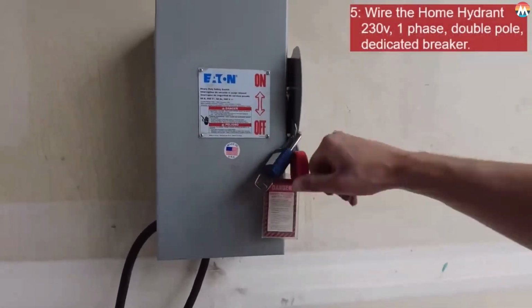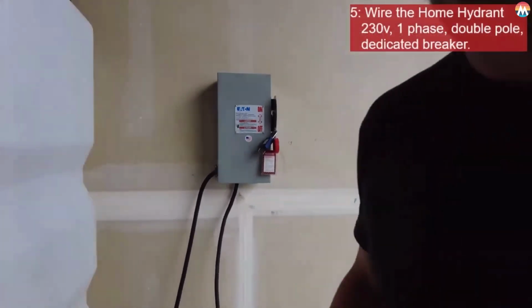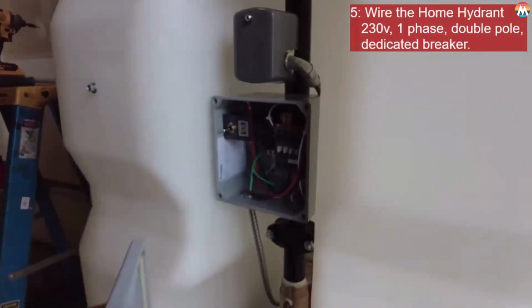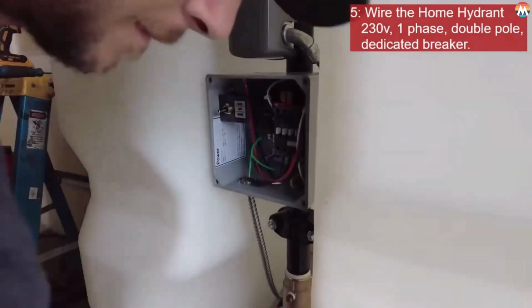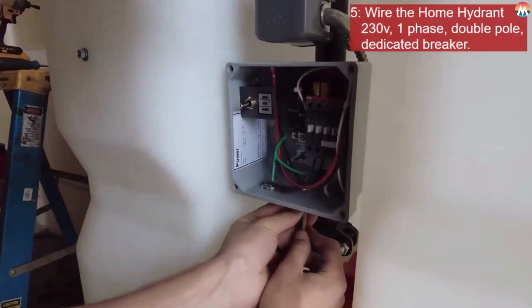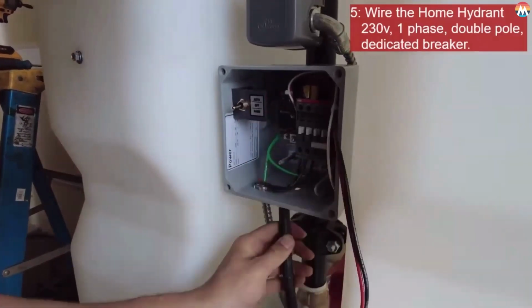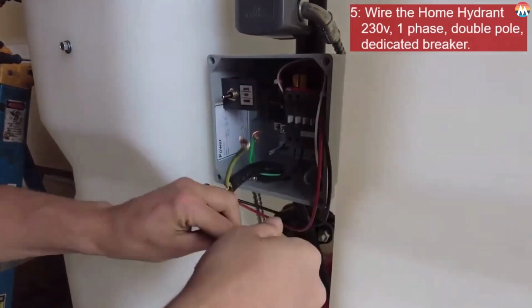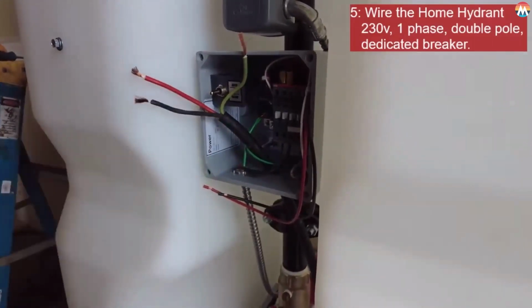Next, we are going to hook the home hydrant up to power. Home hydrants are designed to run off of 230-volt single-phase power. They should be connected to a double-pole dedicated breaker. Always make sure that the power is off before you start wiring up the home hydrant. We drill a hole in the bottom of the control panel to feed the wires through.